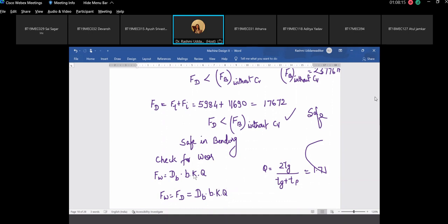So the first way is difficult because for the load stress factor K, you have a table given as 16.6 where the value of K for 20-degree involute full depth is given in terms of the material and BHN. BHN stands for what?